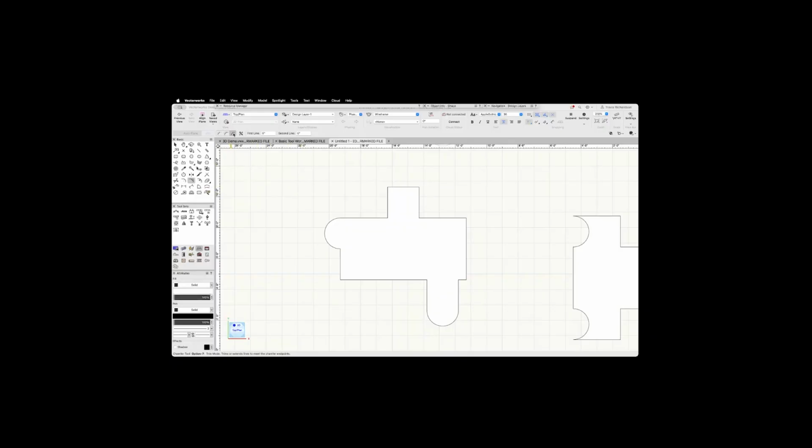Again, there's 3 different modes. We're going to stick with the trim mode just like we did in the fillet tool. And there is a first line and a second line. Right now those are both set to 6 inches. Let's just try and see what that does for us. I think it's going to be too much, but I'm going to click on this first line to start it. The second line, no, that's actually pretty good. We're going to stick with 6 inches there. So obviously I have taken that sharp 90-degree corner off